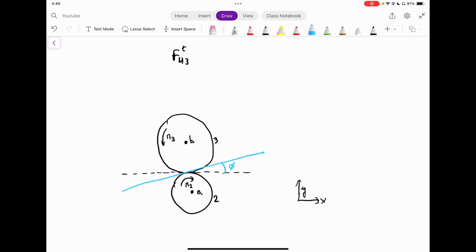And this line gives us our 20-degree line of action or 25-degree line of action, however we want to make the line of action. So usually it's going to be 20 degrees. If you don't know your line of action, I suggest that you guess 20 degrees. Okay, so we have this information now, and we have this drawing.